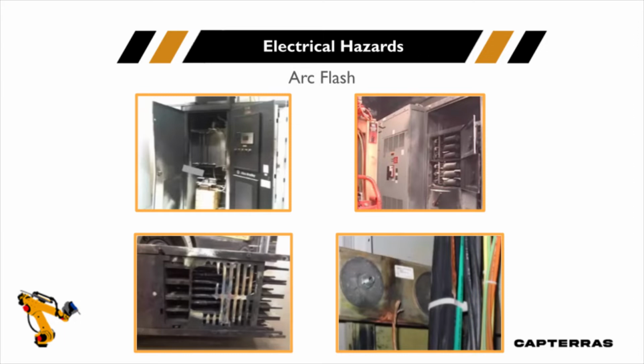Now, one of the points I want to make, when you're looking at a PPE program, even NFPA 70E says in some cases closed doors do not fully protect against arc flash. So we have to consider closed doors, open doors, and the arc flash. We might have a closed door, but that doesn't mean we're not going to have an arc flash. On the upper right, you see a picture of an arc flash that occurred in electrical switchgear when the disconnect was opened up.